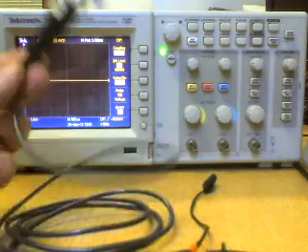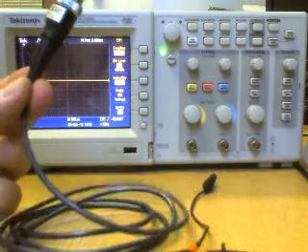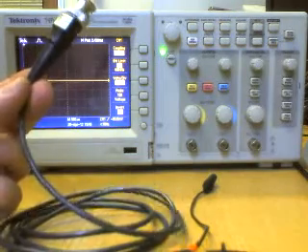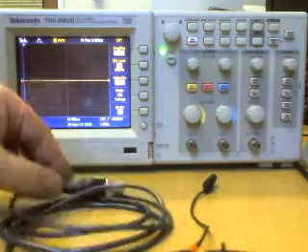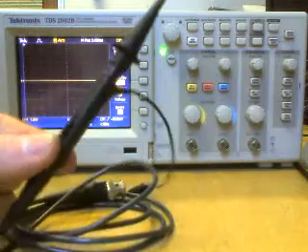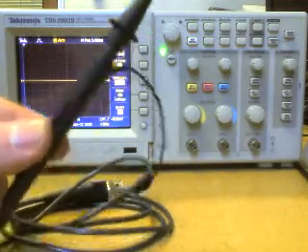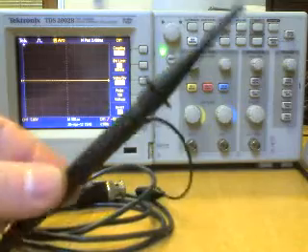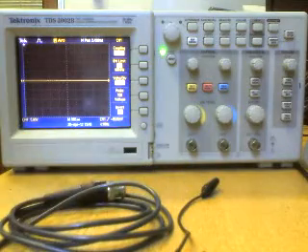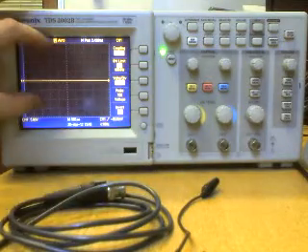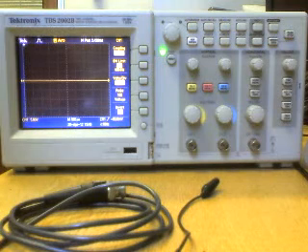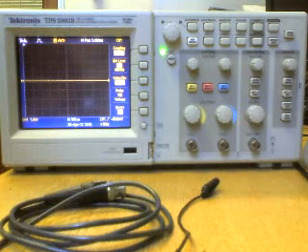But if you use a ×10 probe, these amazing things, okay, you have 80 volts at this end, you'll end up with 8 volts at this end, and it'll be nice and consistent. It'll be a consistent value, consistent attenuation, okay. So our 8 volts will be displayed, so you will be able to see our 8 volts.